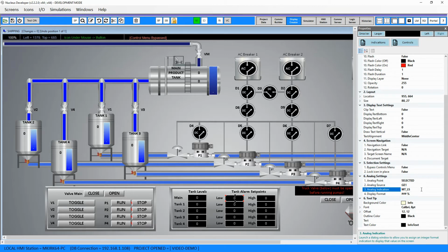When the user clicks on this input box, it goes into edit mode. The operator can enter a value with the keyboard. Floating points will be allowed only if the protocol to the PLC is set that way. Once the operator selects the enter key, the control is then sent. The edit portion disappears and the returning indication displays.